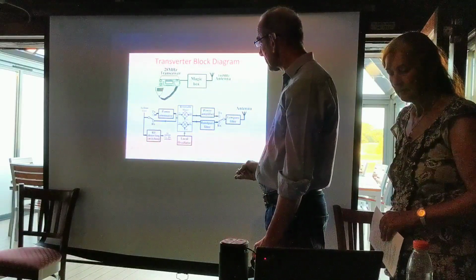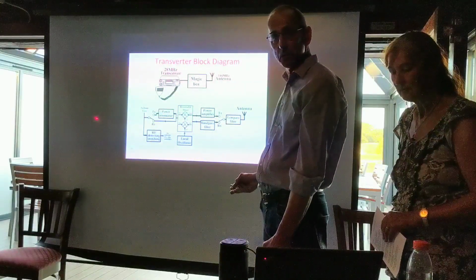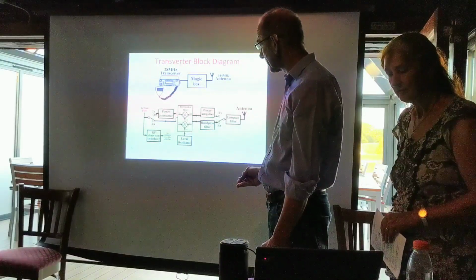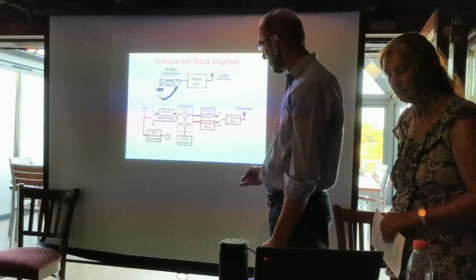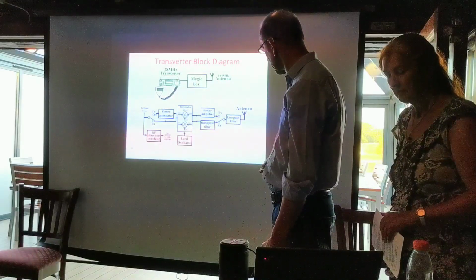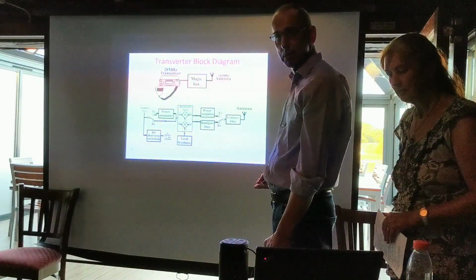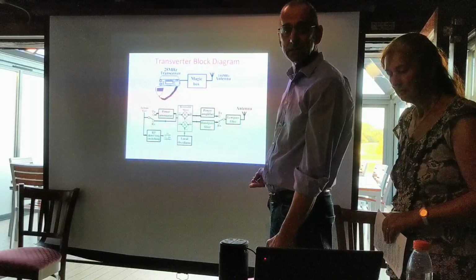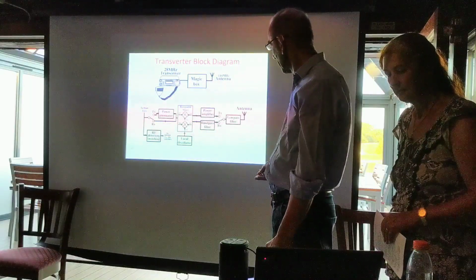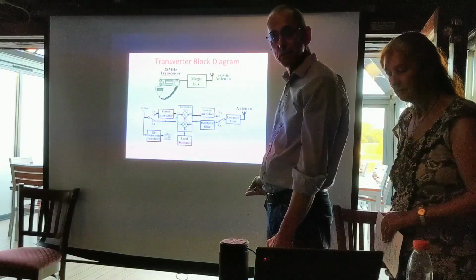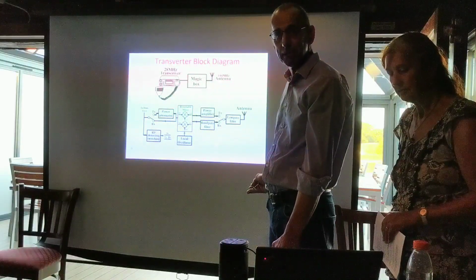Now, when we let go of the PTT switch and go into receive mode, this needs to detect that and switch the thing back. Now the signal from the antenna comes through the low pass filter. Well, it doesn't need the low pass filter, but it doesn't really do any harm, so why switch it out? It then needs to go through a really good band pass filter, and that's what really makes a good receiver, that band pass filter.